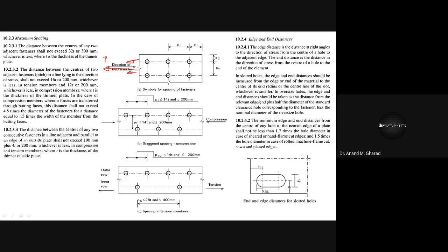So as per your IS code, if the center to center distance between these two bolts is parallel to the stresses which are developed, then it is known as pitch. Got it? So for tension members and for compression members, these spacings are to be followed.